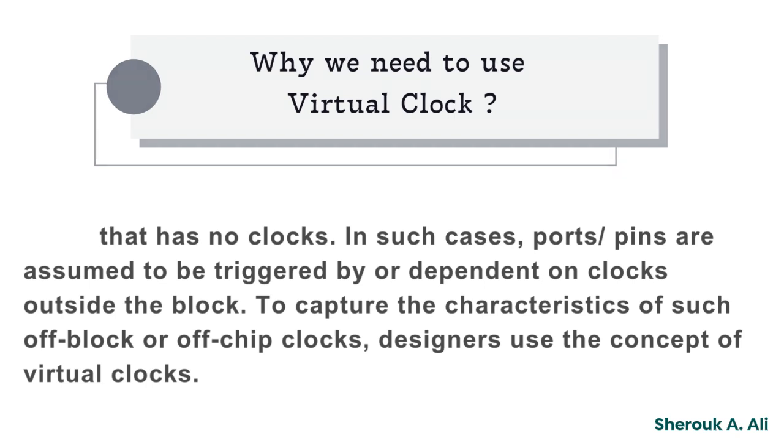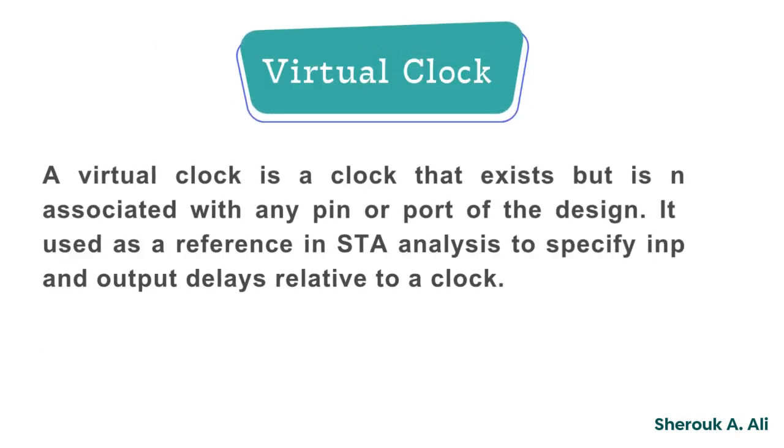So to summarize, a virtual clock is a clock that exists but is not associated with any pin or port of the design. It is used as a reference in STA analysis to specify input and output delays relative to a clock.